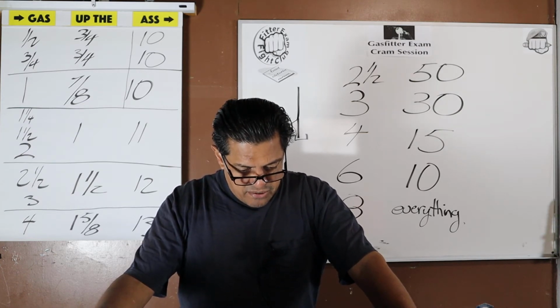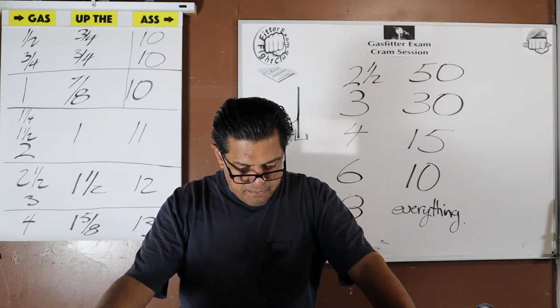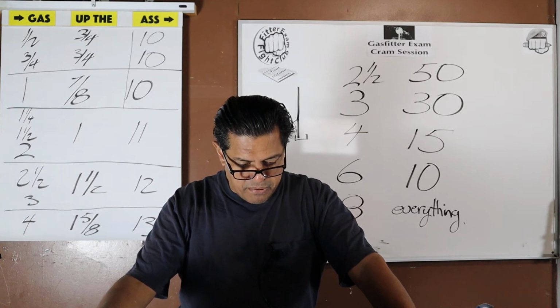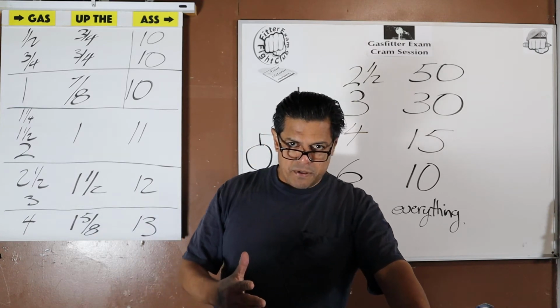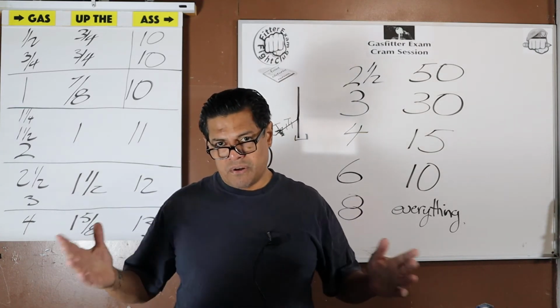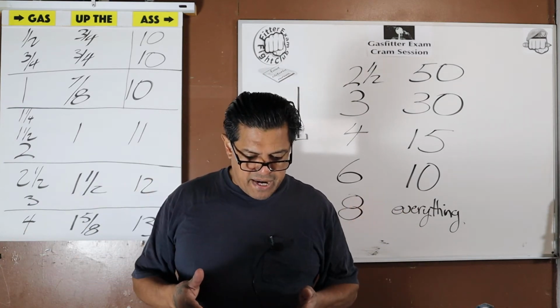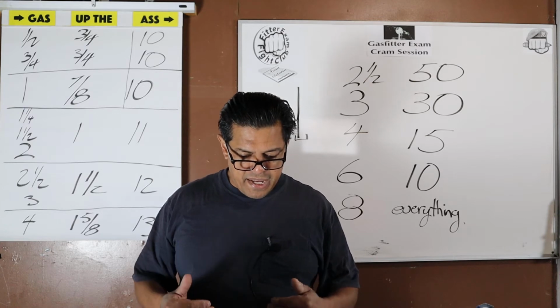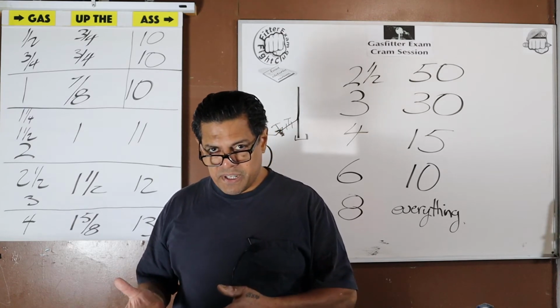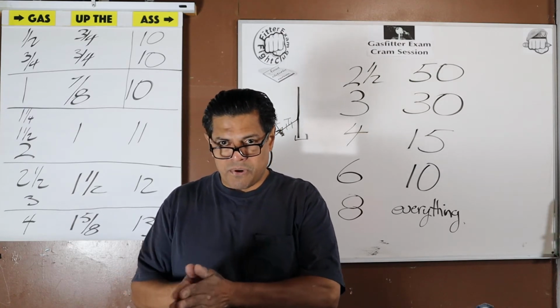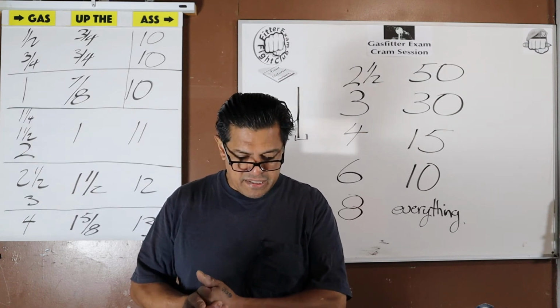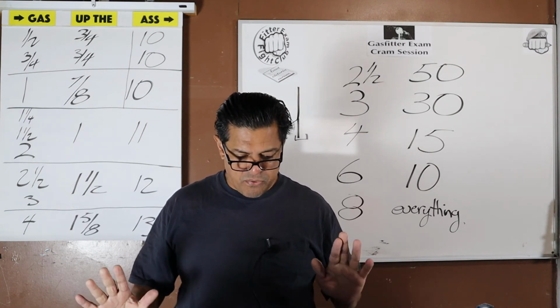Question 8. For steel gas piping, threaded fittings larger than how many inches are not permitted? We're not given a specific pressure, so we're going to go with the largest possible that we could ever use. Here they're asking a threaded fitting larger than, so we know the largest possible fitting we can ever use is a 4-inch fitting. Anything larger than that is not allowed. The correct answer is 4.